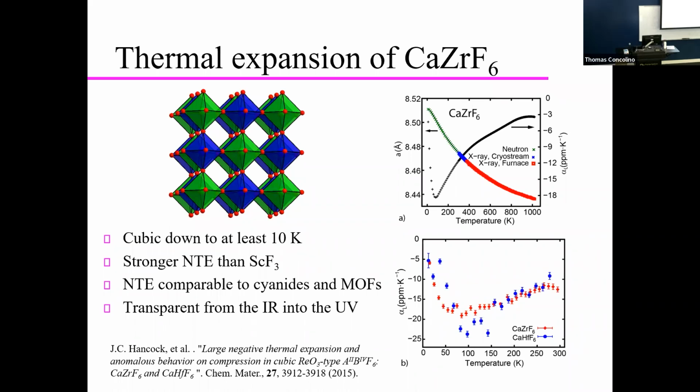Really impressive. So you have here a material with no d electrons on the metal, very big electronegativity difference between the metals and the fluorines. What that means is big band gap, non-optically absorbing out in the ultraviolet. Because it's fluoride, soft vibrational modes, optically non-absorbing to mid-infrared. This material has a really big window of optical transparency. If you process it right, it is processable as a ceramic, as well as showing negative expansion.